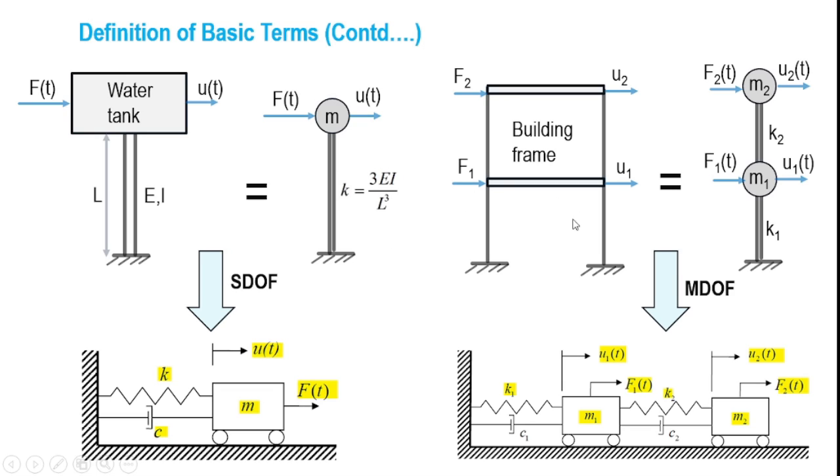And here is another example to demonstrate the use of a multiple degree of freedom system, or an MDOF. Here is shown a simple two-story shear beam model. Here, please remember, the beams are stiff enough that we can almost neglect the beam column rotations, which means that in order to describe the response of this two-story building frame, we require only two coordinates, u1 and u2.